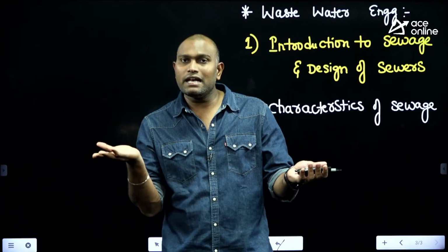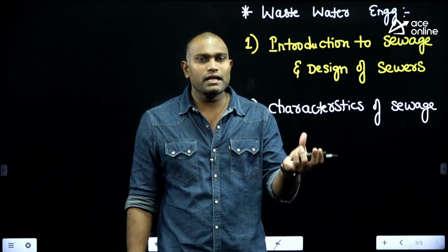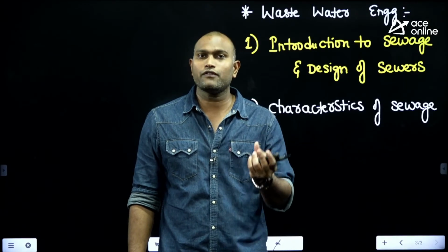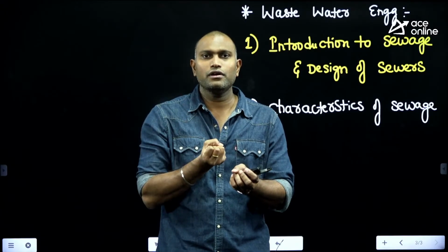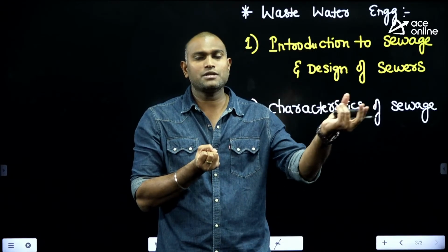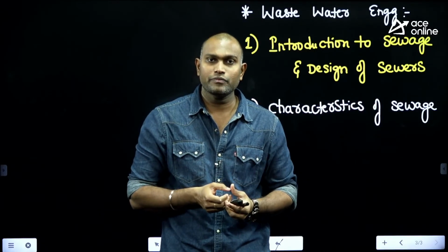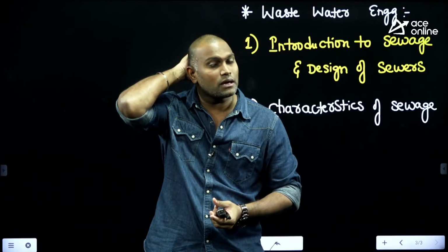So this organic matter is going to be food for the bacteria, and already in the river water a sufficient quantity of oxygen is there. So immediately the bacteria eat the food, under the presence of oxygen, aerobic decomposition, under the absence of oxygen, anaerobic decomposition. So in the river water, it undergoes a huge amount of decomposition.